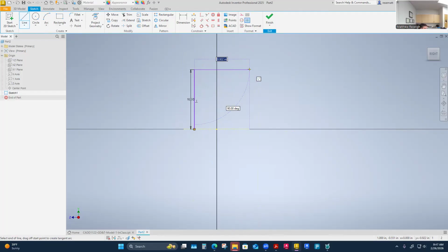So that's 1 inch that I'm horizontal or perpendicular this way, 2.125. That's 2 1/8. And then I've got to figure out how far this comes down. So this is 1 inch. It's really up 3/4 from there on my dimensioning on my drawing, 3/4 from the center axis. So I'm going to go perpendicular. 0.25 is the length I'm going to draw it. That's not perpendicular. Back that up. There we go. Make sure I got my perpendicular constraint showing. Otherwise, I'll have to reconstrain it, which is okay too.